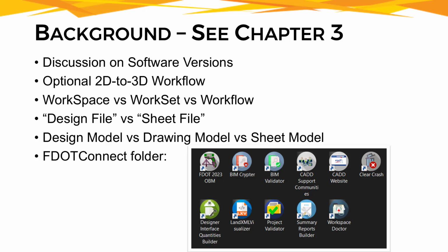I want to specifically mention ClearCrash and Workspace Doctor. ClearCrash is what you should use to crash the program if it freezes, similar to a Control-Alt-Delete. And Workspace Doctor can be used to clear crash as well as delete some user settings and restore them back to default. You can also access which version of Bentley and FDOT software you have installed, as well as access the Workspace install location and Workset folder.